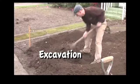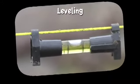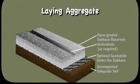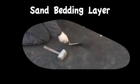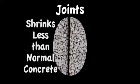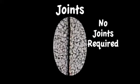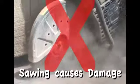The installation of pervious concrete also requires the standard practices of excavation, leveling, setting out the form frames, laying a base layer of aggregate stone, and a bedding layer of sand. Because pervious concrete shrinks less than half the amount of normal concrete, pervious concrete does not require joints. However, many installers place joints every 20 feet as a precaution. Joint tools should be used rather than sawing the concrete. Sawing pervious concrete may cause raveling of the concrete stone, resulting in damage.